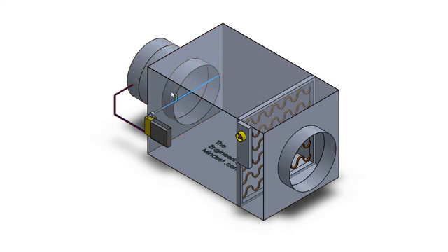The air entering the box, like I said, is around 13 degrees Celsius or 55 degrees Fahrenheit typically, but this temperature can be adjusted via your BMS. Sometimes that isn't warm enough, so we've got an electrical reheater here which will switch on, and it will then just warm that air up as it passes through.